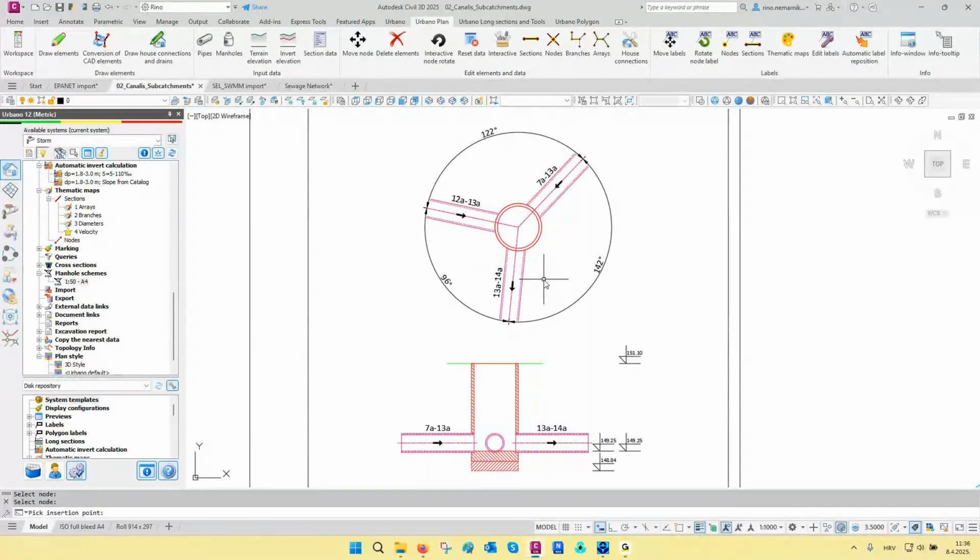But if you don't do that, the program will still have some rules. So it will always go with the biggest pipes and the first biggest outlet diameter, or if this rule cannot be satisfied, it will go with the invert elevations that are the same or close, or it will go with the lowest deflection angle.